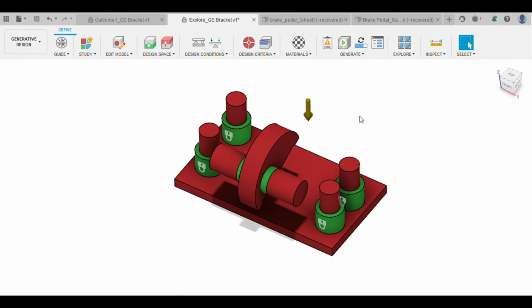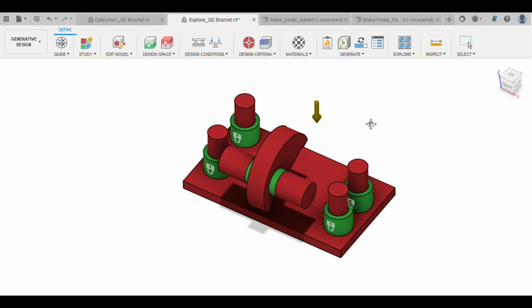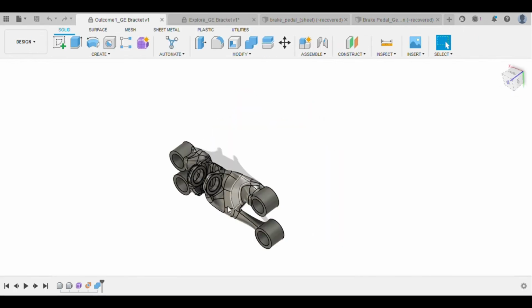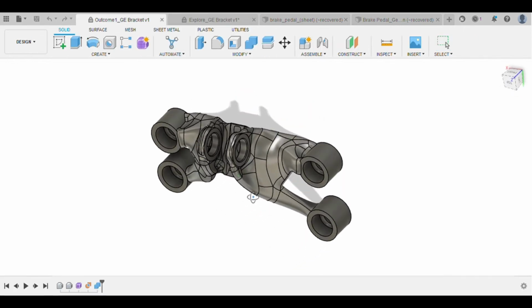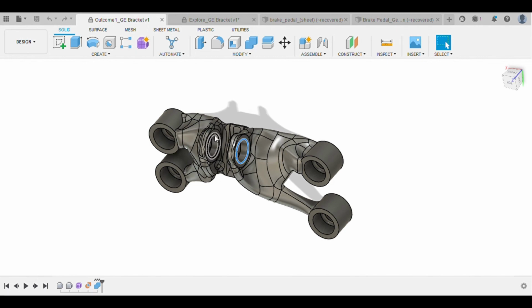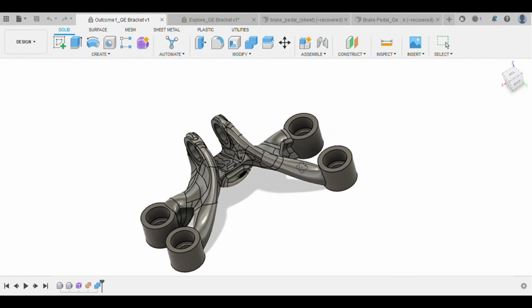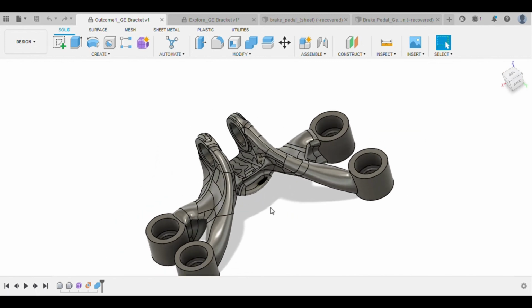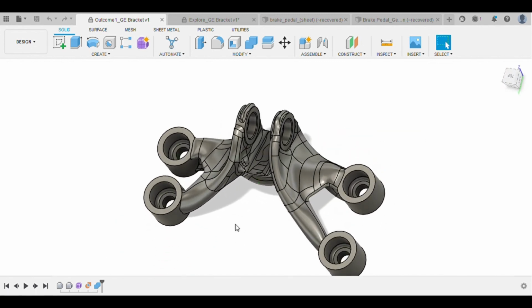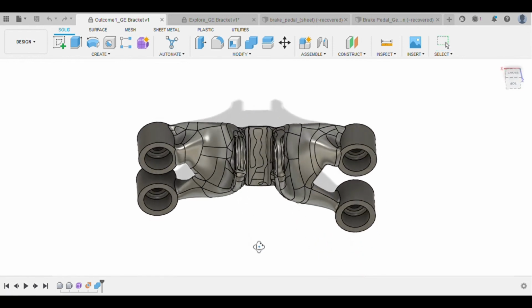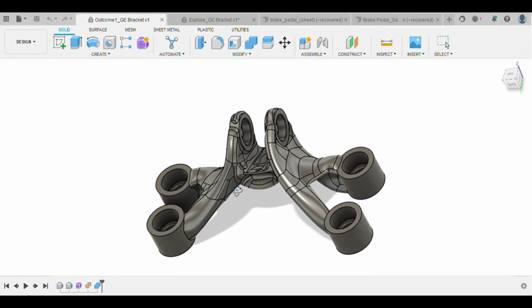Fusion 360's advantage is that this is a cloud based software, so there are no major considerations on the system that you use. So with the help of the internet, the generative design process would happen. So several outcomes are released in the generative process, and one of these outcomes is this. As you could see, in the major parts there are functional requirements. Besides that, looking at the assembling conditions, this is the outcome with the help of generative design. So in this a lot of weight optimization has taken place.